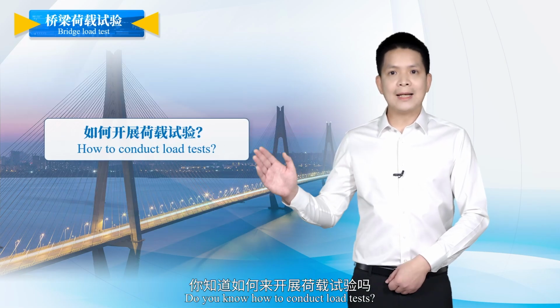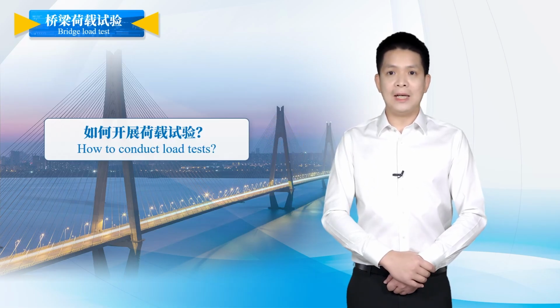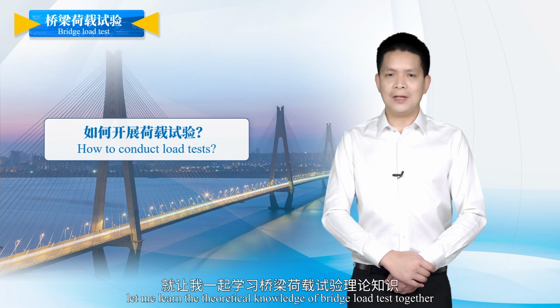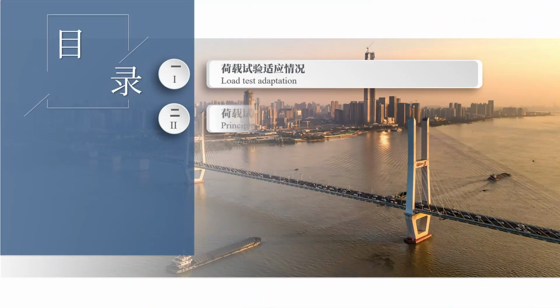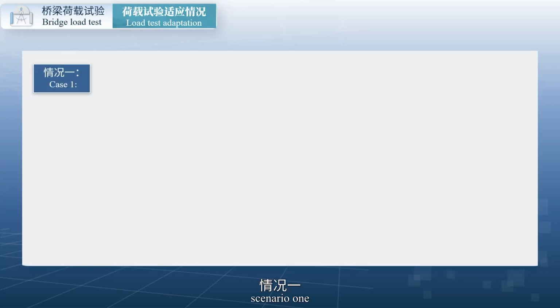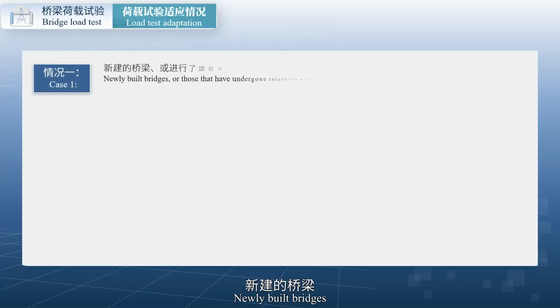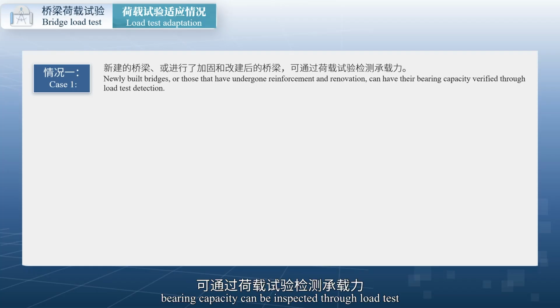So, do you know how to conduct load tests? In this lesson, let us learn the theoretical knowledge of bridge load test together. Load test is applicable in the following two scenarios. Scenario 1. Newly built bridges, or bridges that have been reinforced and retrofitted. Bearing capacity can be inspected through load test.